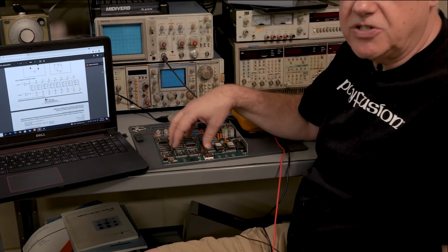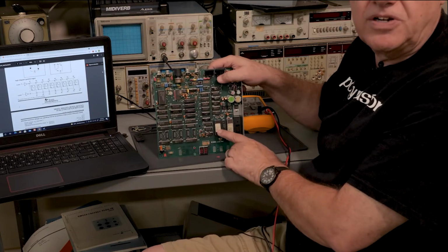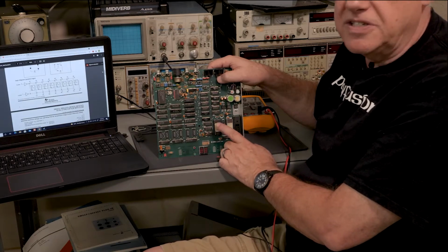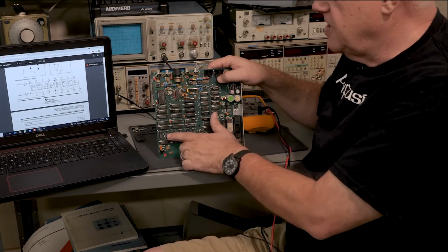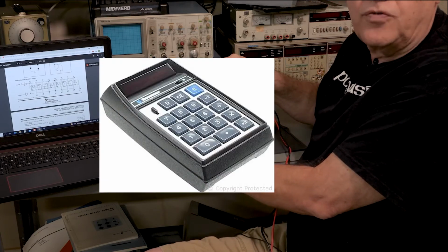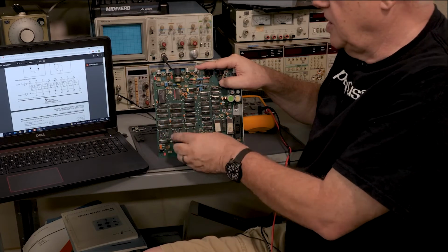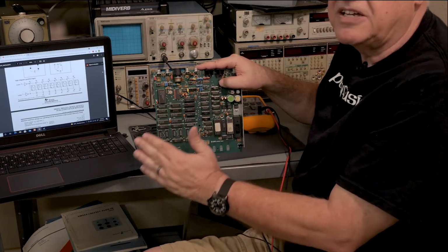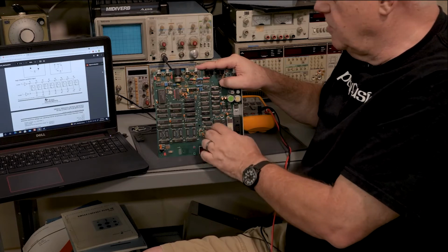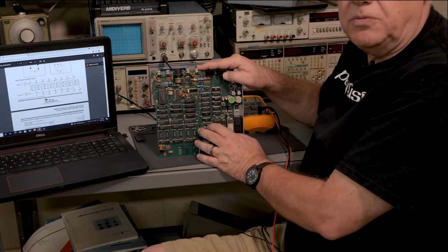And that's what is true in the MidiVerb. Every time the opcodes are fetched out of here, only 2 bits of the opcode is to tell what the instruction is, because it turns out there's only 4 things this thing can do. This is essentially a 4-function calculator. So all the algorithms that we have are simply stacked and repetition of only 4 basic operations. That's only 2 bits needed. What's the rest of it?